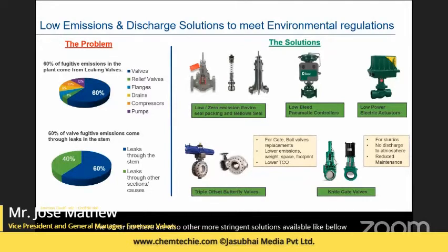And then there are also applications where sometimes there is no instrument air available, or you use single loop controllers which are powered by the process medium itself, like natural gas. Again, you have low bleed controllers available in that aspect as well. We also talked about low power requirements in process plants. Again, there are low power electrical actuators now available which can be used for such applications.